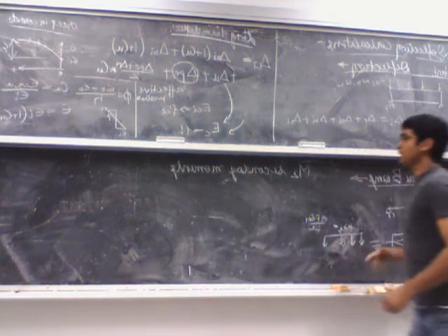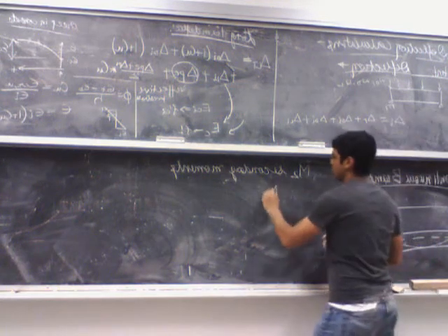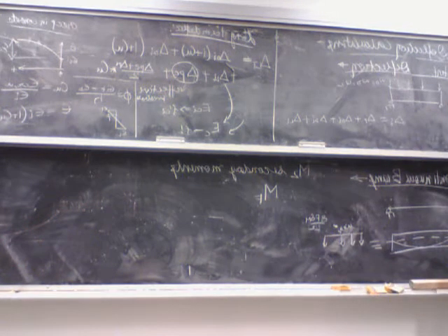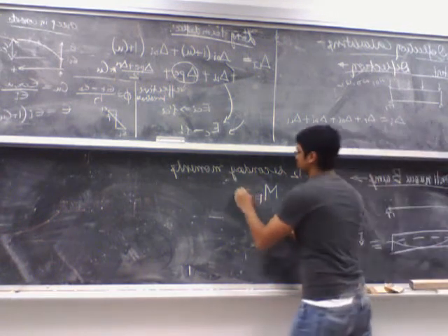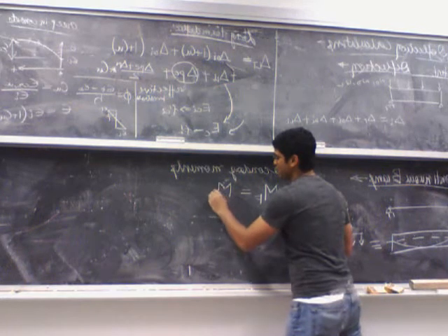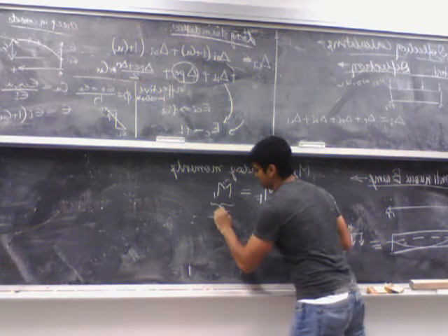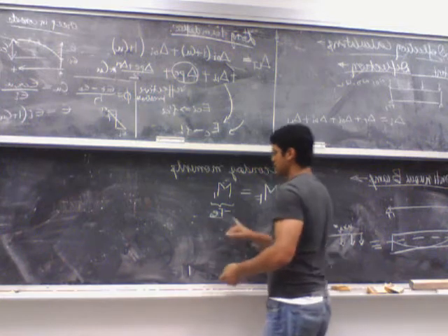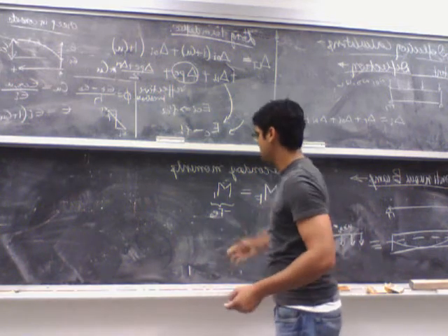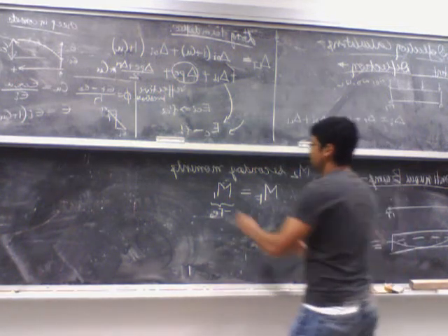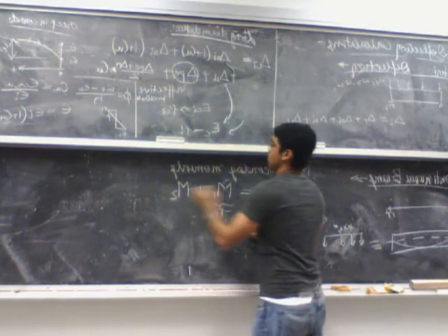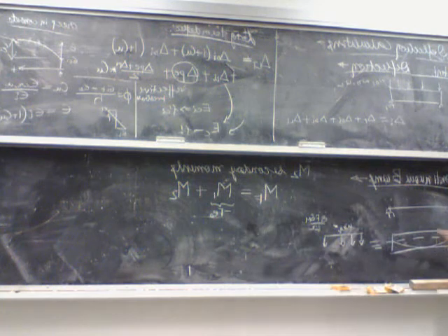So in case of an indeterminate beam, the total moment due to the pre-stressing force and the eccentricity is the sum of the primary moment M1, which is the same as minus F e naught or minus Fi e naught, depending on whether you are looking at the initial condition or the service condition, plus a secondary moment M2, which is simply due to the fact that the beam itself is indeterminate.